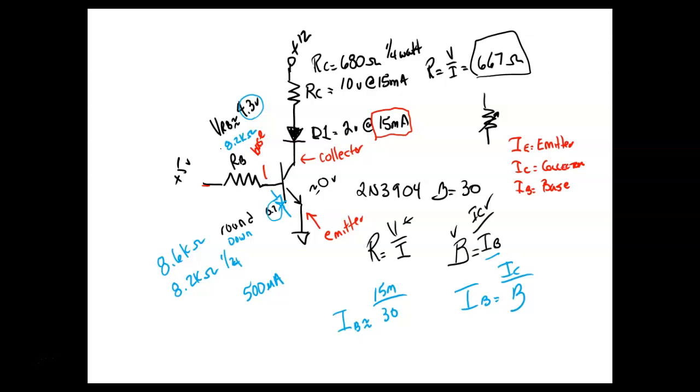Silicon is by far the most widely used now because it's a lot more stable over temperature. So we use Kirchhoff's law. If you apply 5 volts right here, this junction drops around 0.7, then that means that this guy goes up to 4.3.